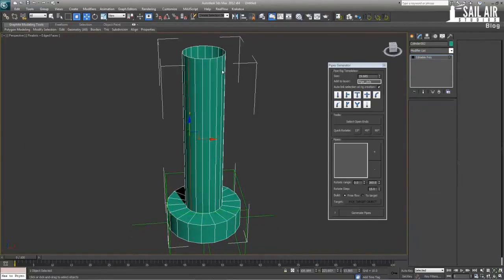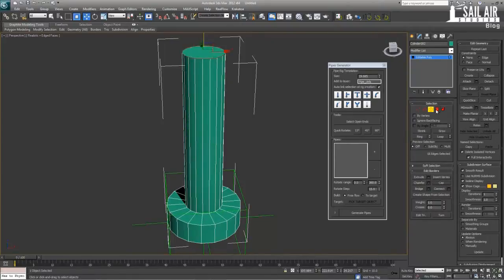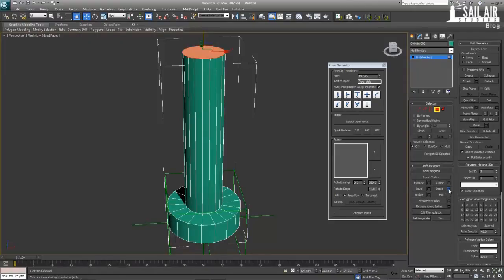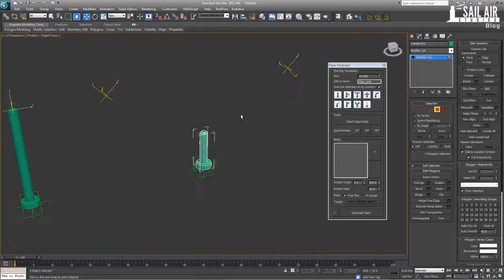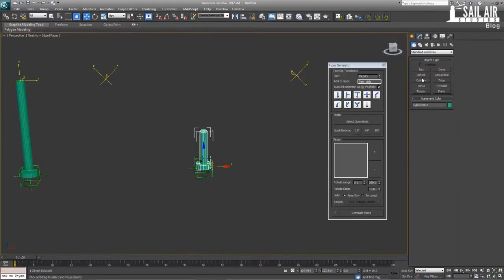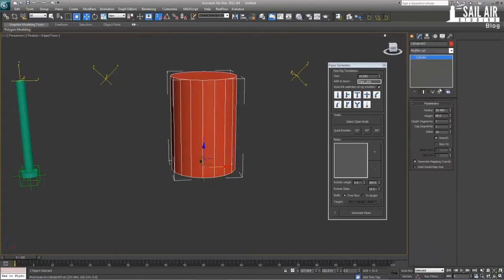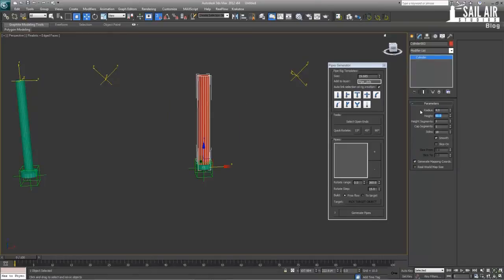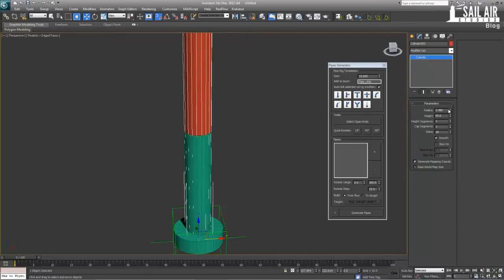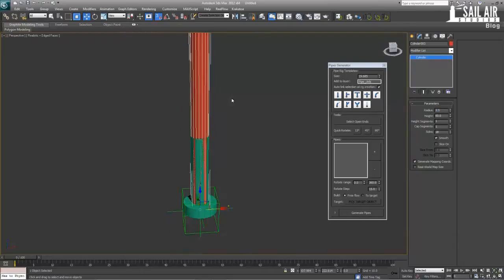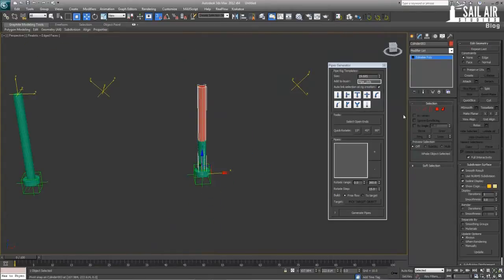However, what I need to do is, since this will be the end piece, I'm going to cap this off and set it by about 1 inch moved up. This just gives me a nice little cap to it like that. Nothing too big. And now what I'm going to do is create a cylinder. Turn on snapping again, just to set it up nicely. Put this down to about 4, I think. Nope, 2. And a bit bigger than that, maybe. How big is this? 2.5? 3? 2.5? I think it's 2.5. Yeah, it feels like it's 2.5. Yep, 2.5. Convert that to an editable poly.